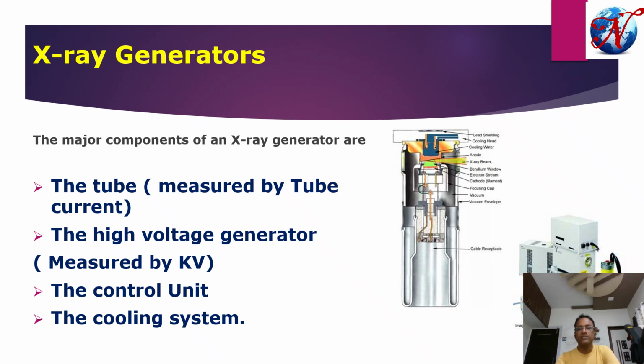Here, the intensity of the radiation, which is proportional to our exposure time, depends upon the tube current, denoted by milliampere, and the penetration capability of the X-ray depends upon the kV value, and that kV depends purely upon the potential difference between the positive and negative terminals, the cathode and anode. So when we talk about the X-ray machine, there are two parameters: one is the kV and the second is the mA.